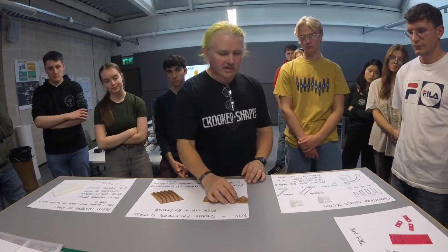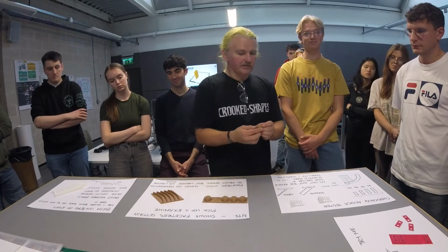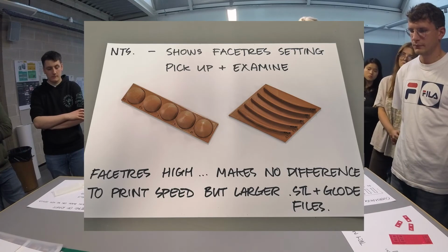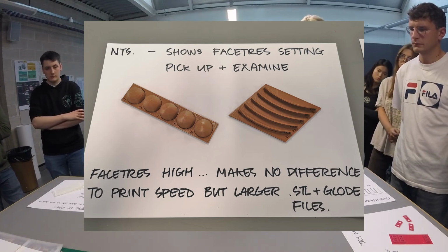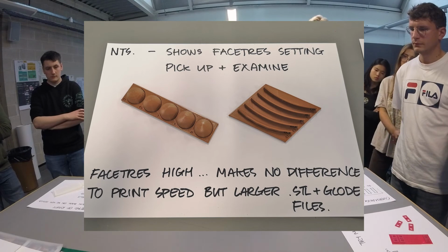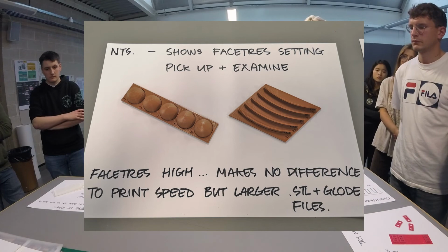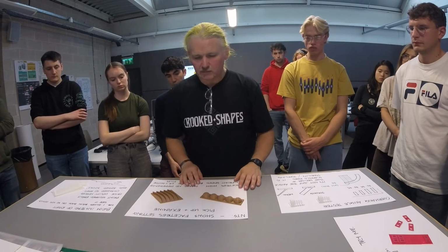So, depending on the size of the object, you might need to go to a facet resolution of 5 or 10 so that you get something smoother. That doesn't impact the speed of the printing because it's about the same amount of material and the same amount of movement. It's the file quality, but the file sizes can jump dramatically. That's usually not an issue nowadays either. Storage is not a problem.